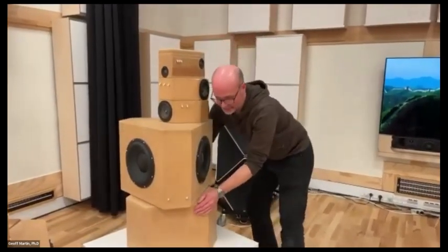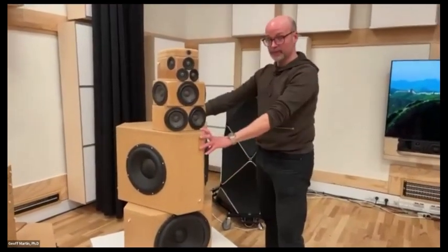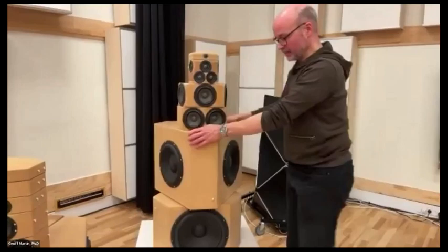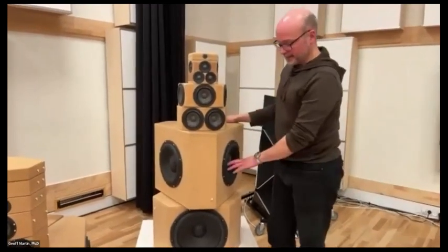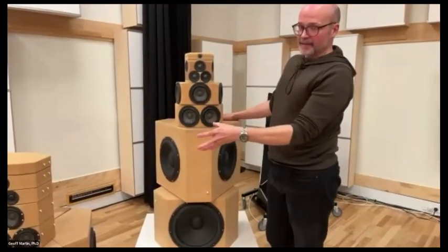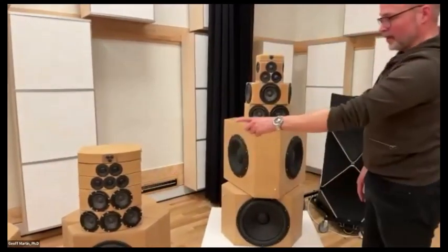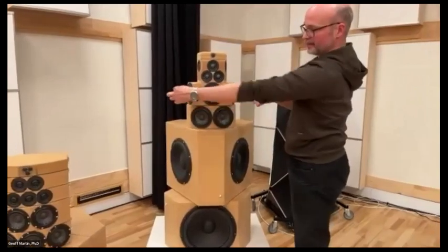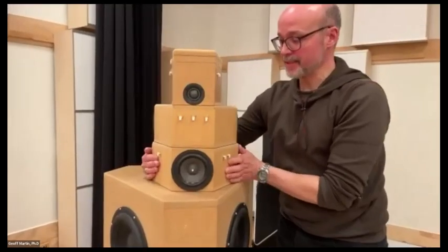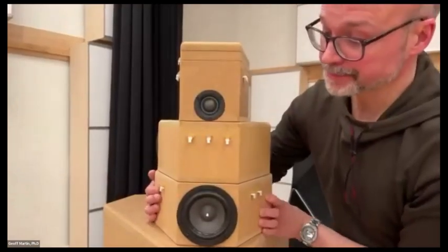And in essence, what we're headed for here is using 1 woofer as the main driver and 3 more to control the directivity. Of course, they're helping provide output. They're not just being used for beam width control. So 4 woofers in total rather than the previous 3. We didn't want to use more drivers than we had before. So we had 5 in the front and 1 in the back before. We changed that arrangement to have 3 plus 2 plus 1. So we still have the 6 mid-ranges and 6 tweeters, 3 plus 2 plus 1.